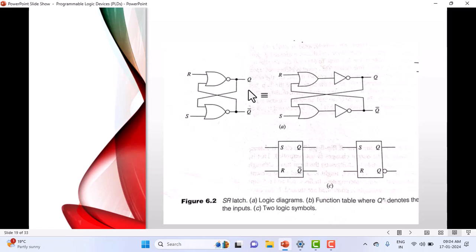Just look at this. Same circuit I am drawing here. Yes. Observe here. This is the Q which you have labeled. This is the Q bar. I've taken this as 0 and this as 1. Don't make noise, please listen here. 0, 0. What does our NOR gate truth table say? For 0, 0, let us say inputs A, B and output Y.